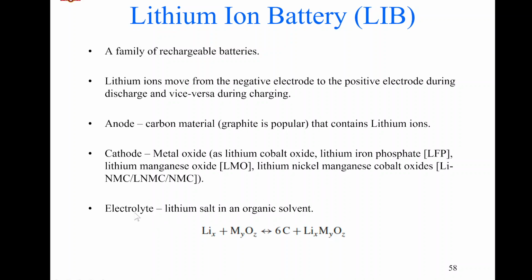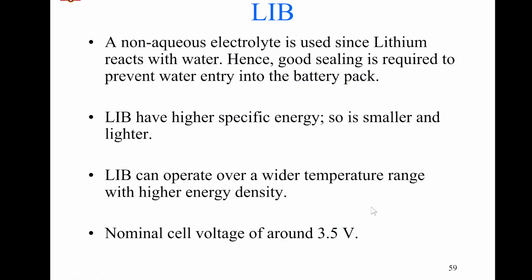like these. So the electrolyte is lithium salt in an organic solvent, and this is the reaction amongst the same, where M denotes a metal. A non-aqueous electrolyte is used since lithium reacts with water. Hence, a good sealing is required to prevent water entry into the battery.